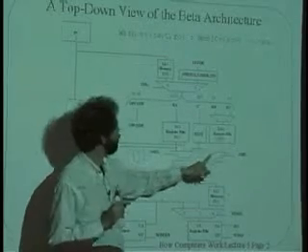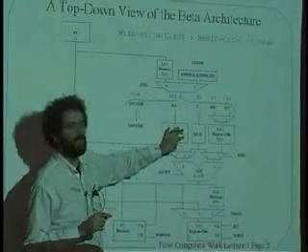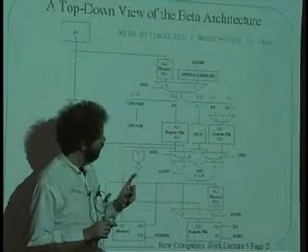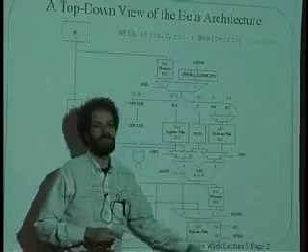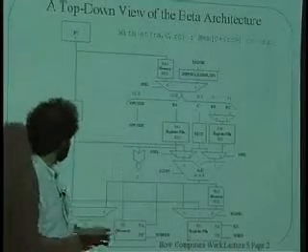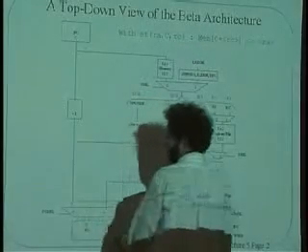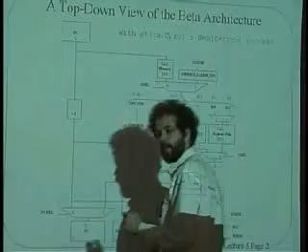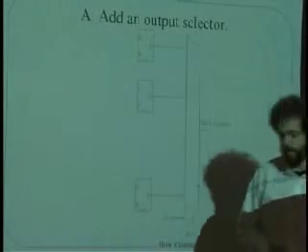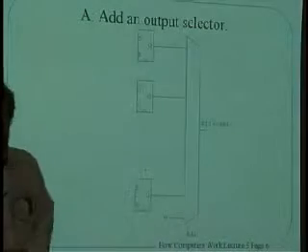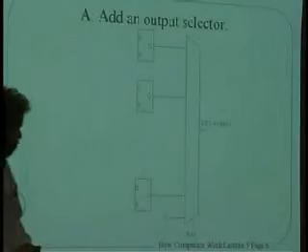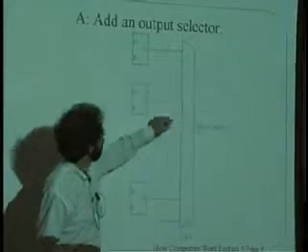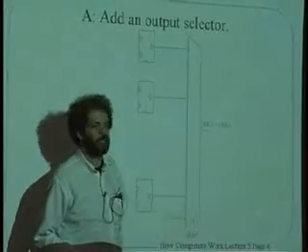And so the first question that comes to mind is, if I'm going to build this thing out of 32 units which look kind of like the program counter here, where there's just a 32-bit number held in one thing, if I'm going to build it out of those, how do I choose which of the 32 gets read by any one of those read ports? And the answer is actually very simple, and you've already seen the part which allows you to do this. It's called a selector or a multiplexer.